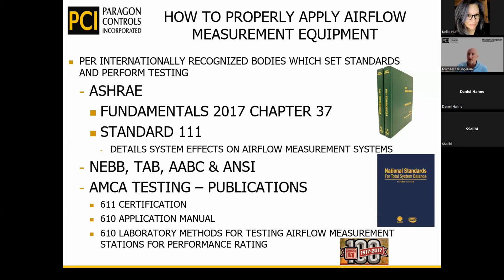Most of what I usually talk about is out of the ASHRAE Fundamentals. The last time Fundamentals was published was in 2017. If you go to chapter 37, you'll find all the information about airflow measurement in there. There's also a long publication called Standard 111, where they test various manufacturers, different technologies, and they come up with how system effects affect different types of products, different technologies.